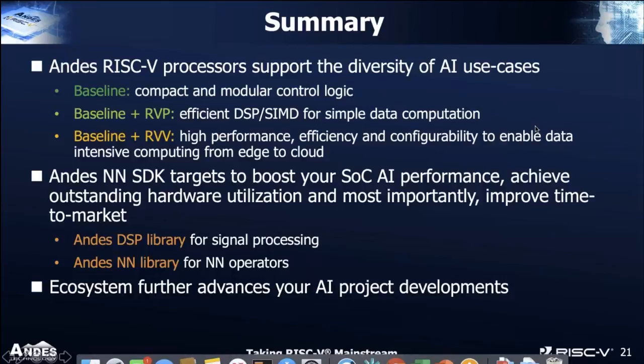Moving on to vectors, same 28 nanometer technology, 1 gigahertz, 512 vector length, running kernel functions like vector add, convert, and vector floating point multiply accumulate, we could almost achieve 340 gigaflops per watt. So the performance efficiency for the largest processor is much better, almost 5 times the small processor. Performance efficiency is higher as you go into more features and start executing higher level software.